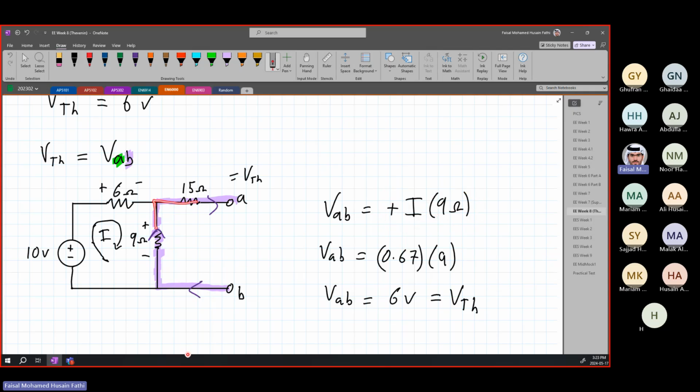And then we move here going to A. Since we have no current flowing through here, since this is theoretically open, this resistor has no voltage drop or gain effect. And then we reached our node A, and we found our VAB. So this is how you find VAB. You will apply this to almost any type of circuit you have. And we'll see an example where we don't just have a resistor here, we also have a voltage source, so you guys just understand how you will be applying it.